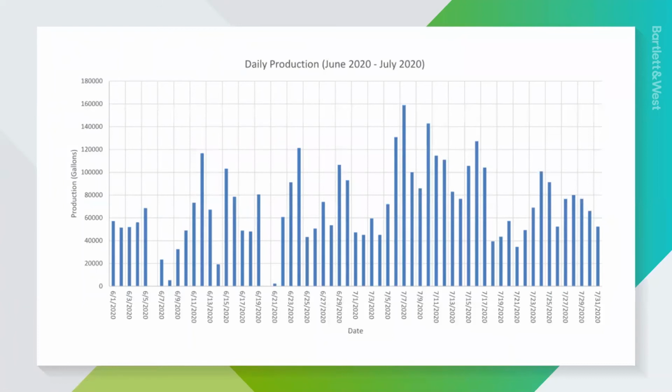Okay, the first thing, this is using SCADA data, looking at this particular service area over the course of 2 months, June and July, and looking for peak days, because we didn't know, is this something that happens once a month, 3 times a year, 10 times a year, 30 times a year? And really what this told us is there was about a handful, 7 or 8 days, where the usage in this service area was exceeding what was in our model and what was designed.